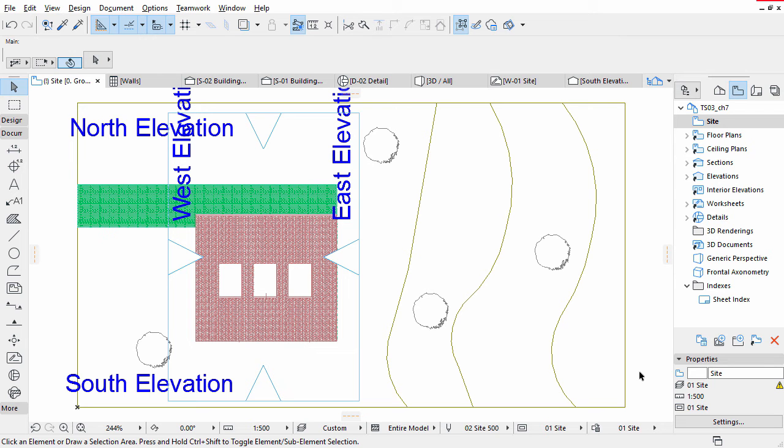Option 1, we save the view with a custom layer combination. This seems to be a quick solution, but later on, if you have different custom layer combinations, you cannot follow which is applicable for which view. Option 2, we update the layer combination. This is the suggested way, so let's do it.